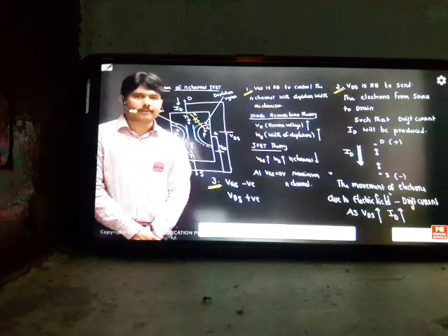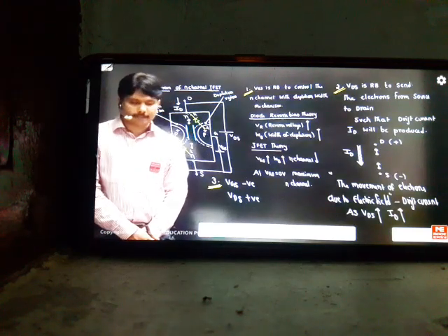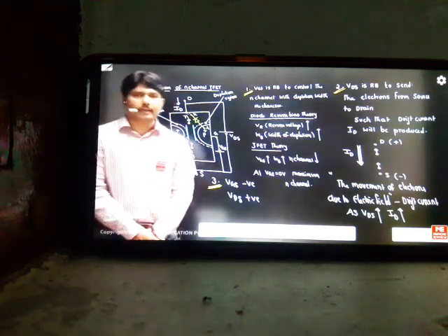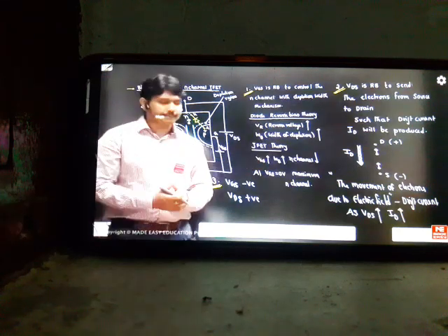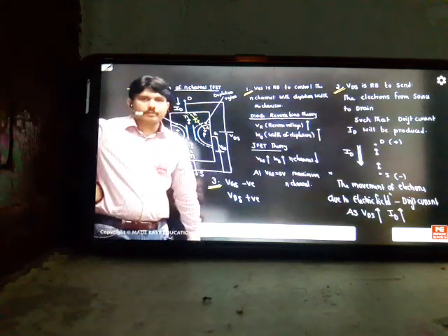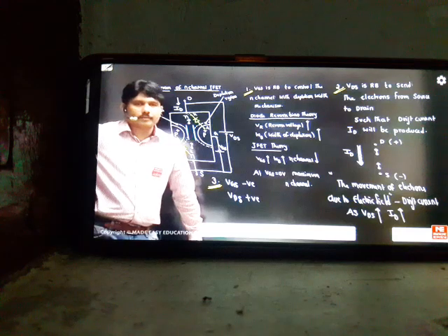Electrical students mainly, I hope you understood the visualization of the N channel JFET, how to understand it, the device part. Okay? What is the reason behind input reverse biased, output forward biased? Why should I do it like this? That means gate to source is not responsible for giving the current. Drain to source is responsible for giving the current.